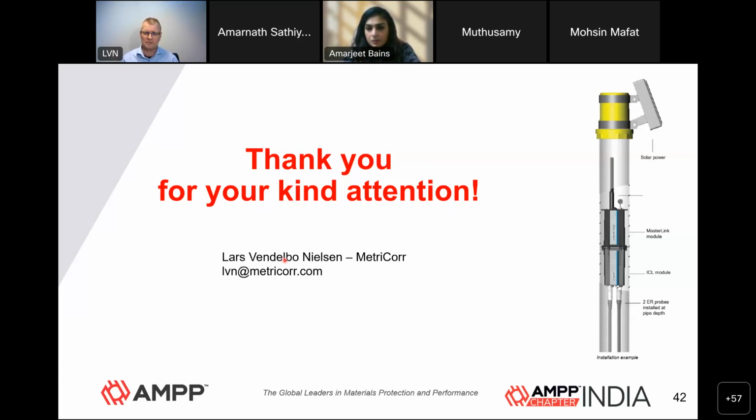As long as you don't have any loss of thickness on your probe, the standards tell you that this is allowed as documentation that your cathodic protection is under control. Remember, as I mentioned in the first place, we need to focus not so much on potential and a little bit more on corrosion rates. The benchmark for cathodic protection is a corrosion rate which is less than 25 micron per year.